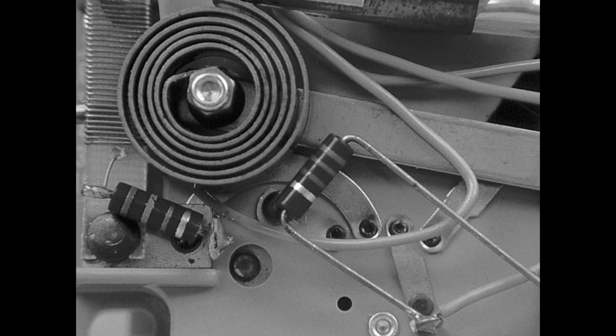Okay, this is an example of a heat anticipator with a helix coil. Okay, that little resistor is actually a cooling anticipator. It provides a little bit of heat when the system is not operational, so that the thermostat will come on slightly before the set point is reached, and it helps keep more accurate inside temperatures.